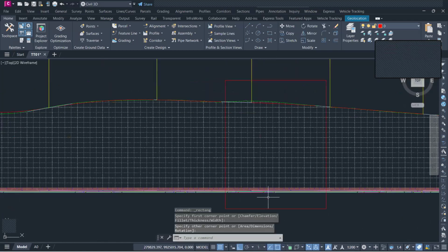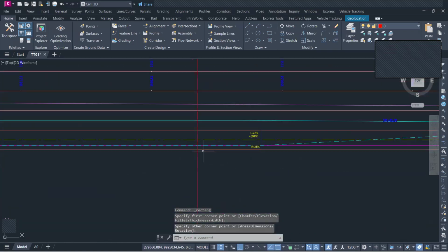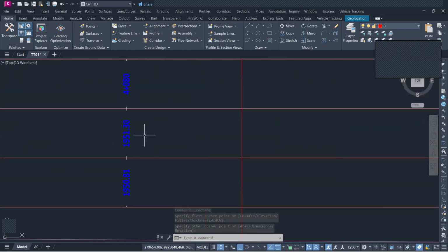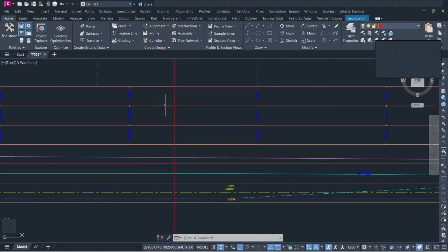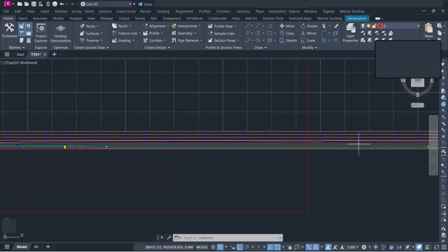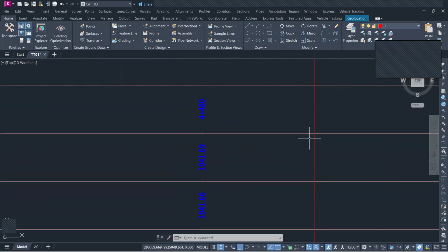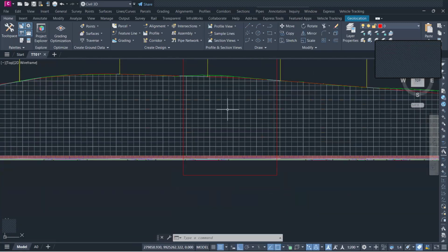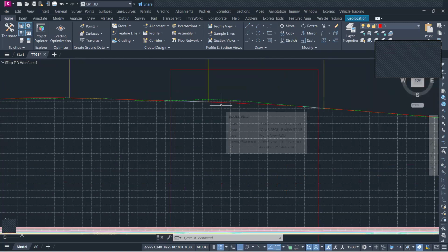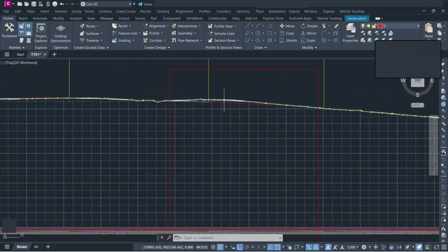He will tell you at this chainage, let's say from kilometer, this is kilometer what? This is kilometer 4 plus 100 or 4 plus 90 all the way to kilometer, let's say 4 plus 480. That material at that point is unusable for this project. It is not suitable for use or for reuse as a subgrade or even as any pavement layer.